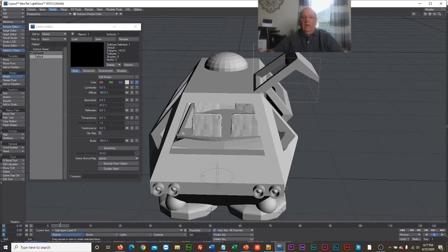So if you were to, in fact, I've seen it worse, depending on how big the model is. And so what's happening is the pivot point for that object is down here, and the door is up there. And so we've got to move that pivot point to make this work. And so this is one of the things that comes up with multi-layer objects. And this comes up typically in layout. So if I go to Modify here, Move, Pivot. So you see I can move the object.